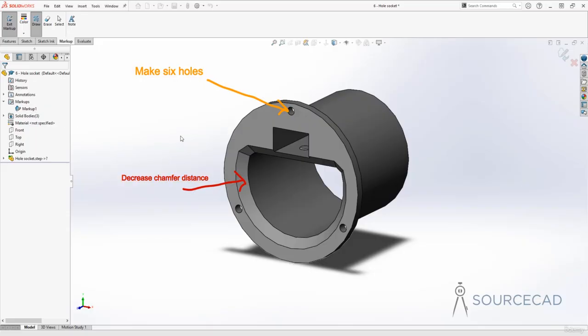So basically I've added 2 separate markups, but SolidWorks will think of it as a single markup because we have added it in just one single view. So now if you want to add another markup in a different view, then you need to first exit out of this markup environment. So I'll just exit out of this, and we have got this markup 1 added here.